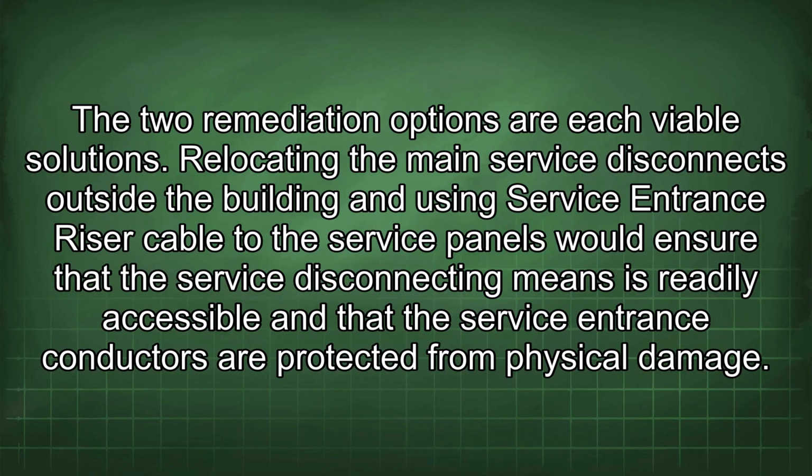Relocating the main service disconnect outside the building and using service entrance riser cable to the service panels would ensure that the service disconnecting means is readily accessible and that the service entrance conductors are protected from physical damage.